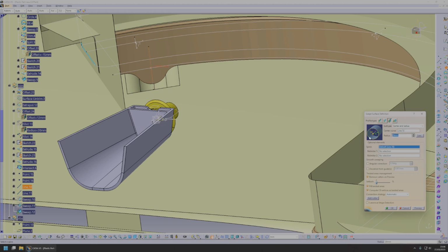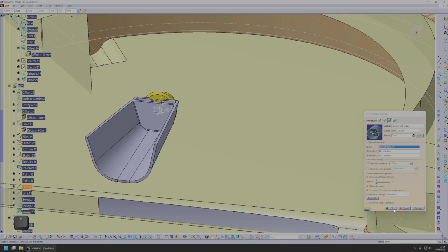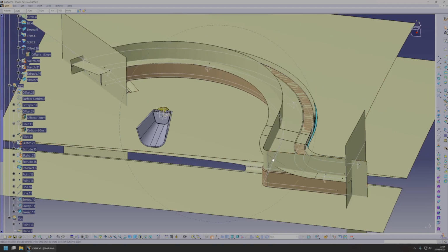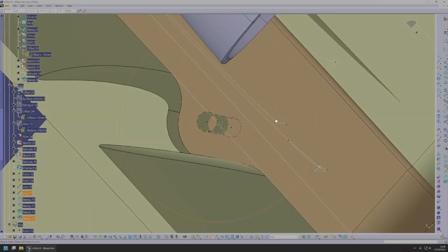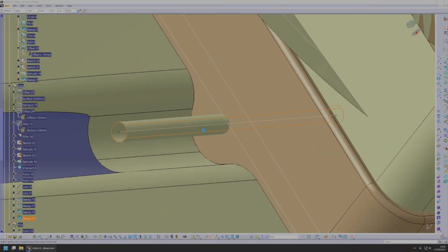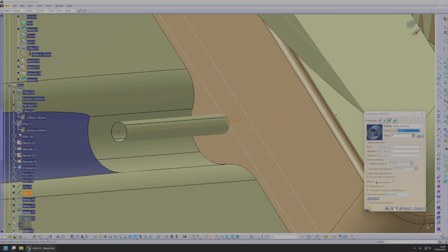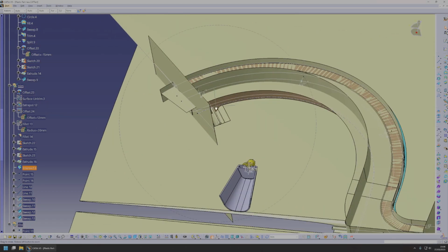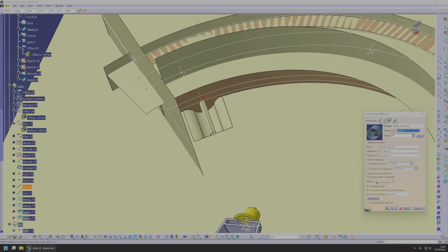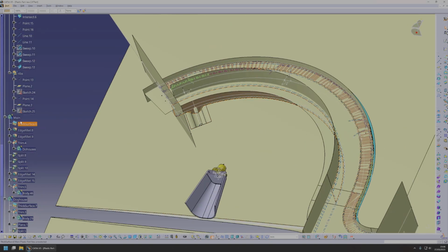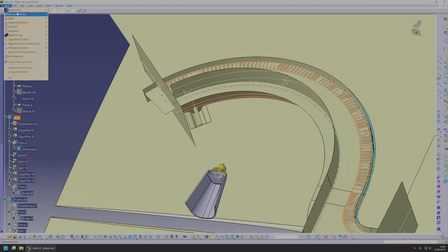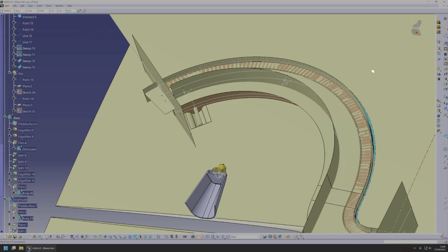Okay, now probably need to create a hole as well. We're gonna go with radius 5. Same here. I don't know, man. Maybe 5 is a bit low. 6. It is a clearance hole. And now we have a choice. We can either do it in the body or do it in the surface. I think I'm gonna do it in the body now.